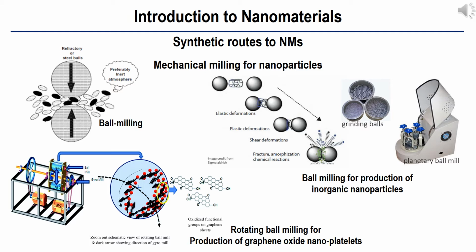Here we will review the mechanisms presently believed responsible for formation of nanocrystalline structures by mechanical attrition of single-phase powders, mechanical alloying of dissimilar powders, and mechanical crystallization of amorphous materials. The two important problems of contamination and powder consolidation will be briefly considered. Mechanical milling is typically achieved using high-energy shaker, planetary ball, or tumbler mills.